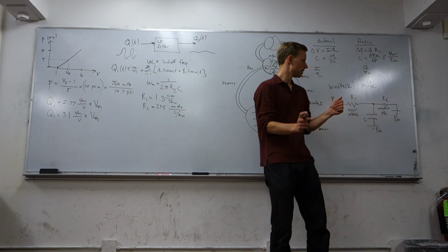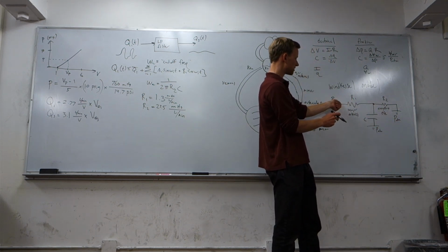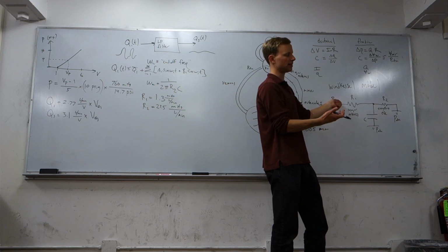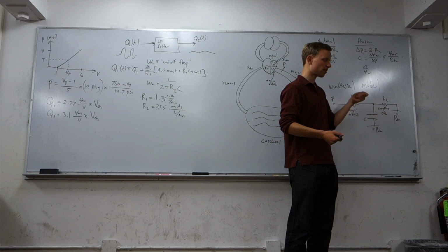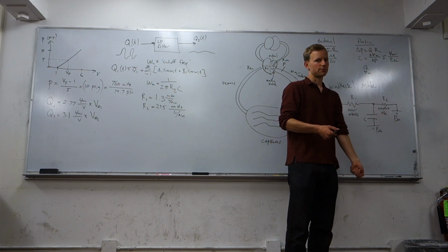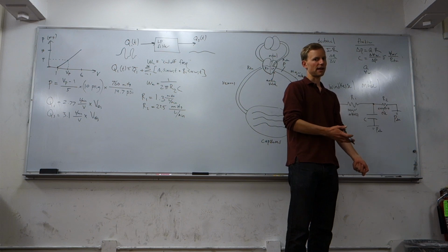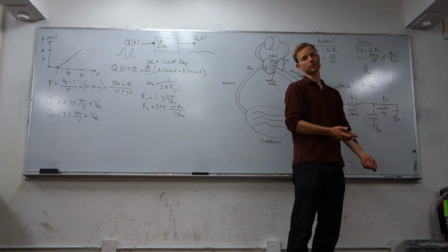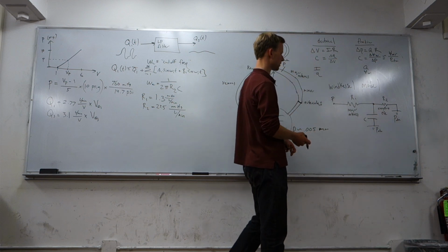Now this is important because the pressure sensor gives us a pressure, and it assumes that the zero pressure is PATM. We're going to assume that the output is also at PATM. If we stick the output of our tube under the bucket of water, then the output will be at a different pressure than PATM. It will be at rho GH. So we have to make sure that the output is indeed at atmospheric pressure.